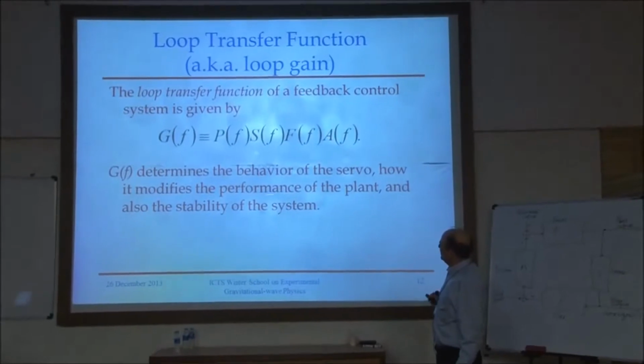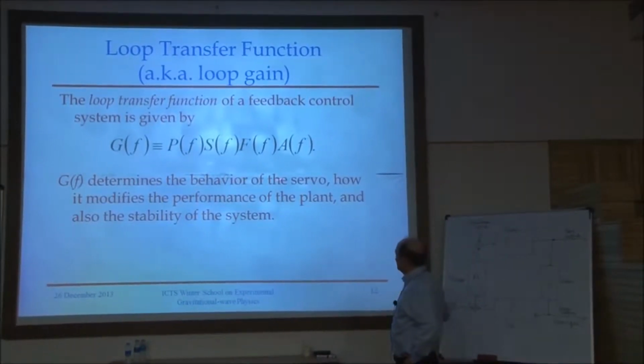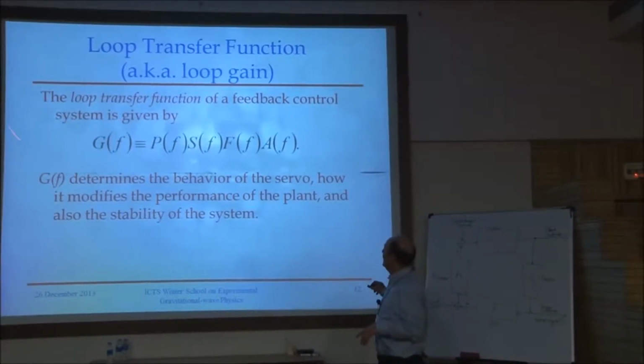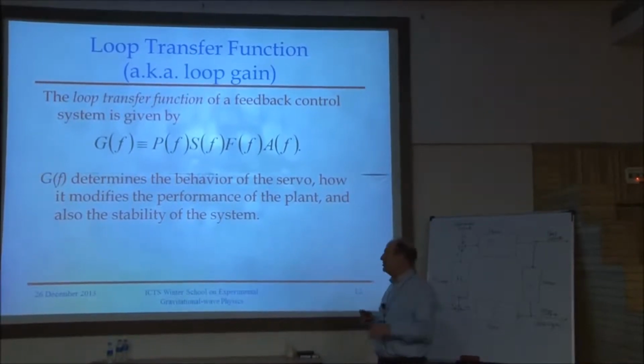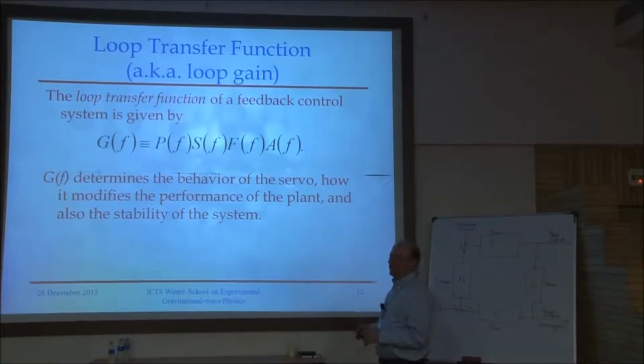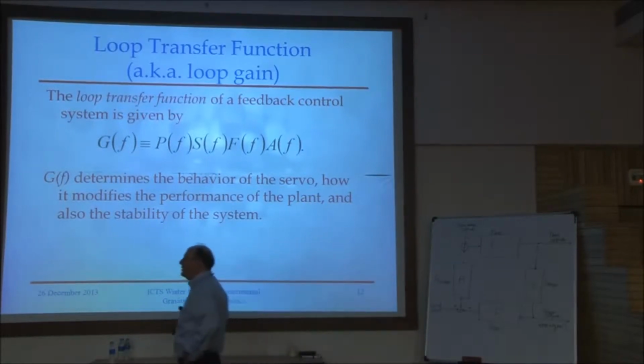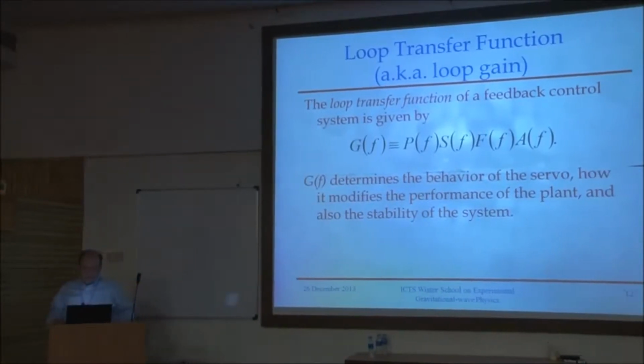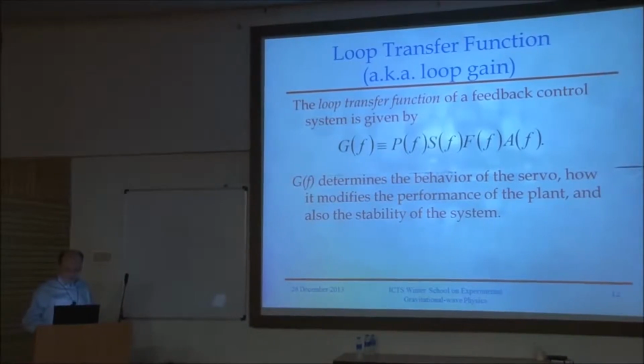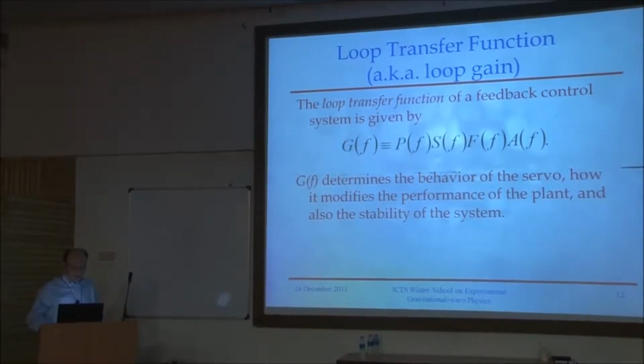And that's a mathematical fact, but there's a deeper fact of feedback systems, that this particular product, the product around the loop of all the frequency responses, which goes by the name, usually it's written G, unless you've already used that for something else. And in the books I was trained by, this thing is called the loop transfer function. Colloquially, on the lab bench, people would usually call it the loop gain. Anyway, this object is by far the most important thing you need to look at. Studying the values of G of f as a function of f tells you essentially everything you need to know about this servo, at least when it's properly operating in the linear regime, which is where these tools work.